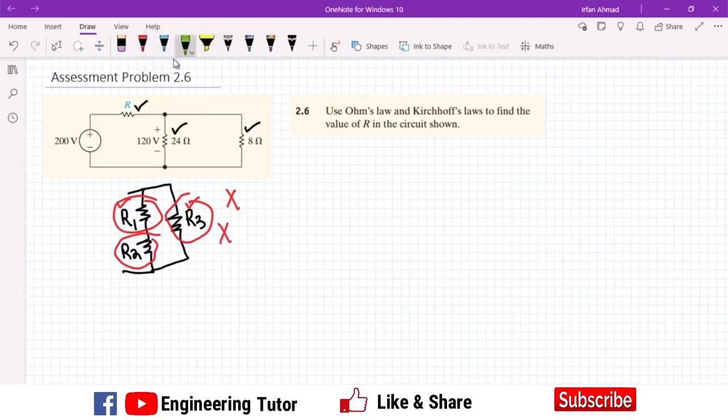To find the answer to this question, there is a concept which you have to understand: two resistors can be in parallel if their end to end points are connected with each other. So these are now in parallel. If this is R4 and this is R5, then R5 and R4 are in parallel, because this is the one end and this is the second end. Similarly, for R5, this is one end and this is the other one. These two are shorted, and similarly these two are shorted. So these two are in parallel.